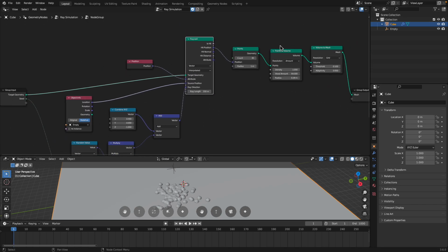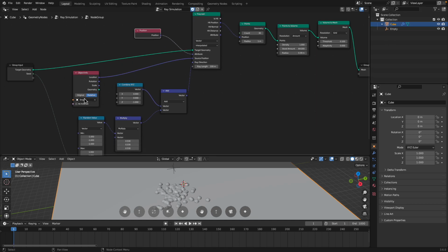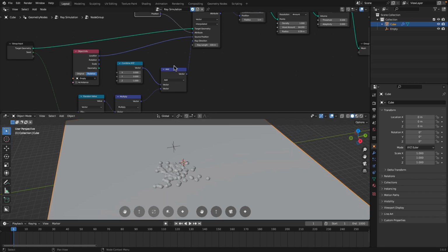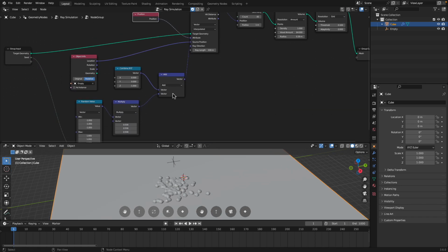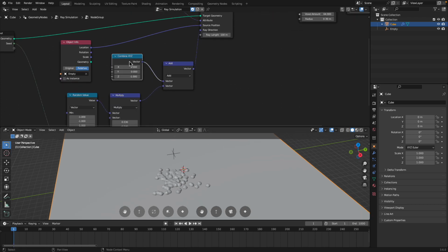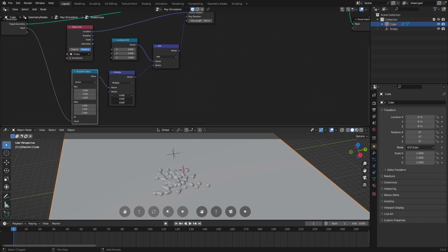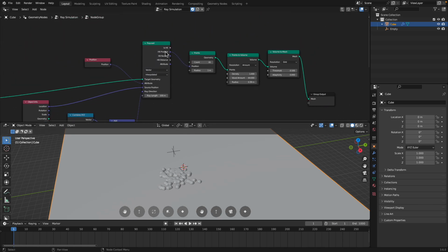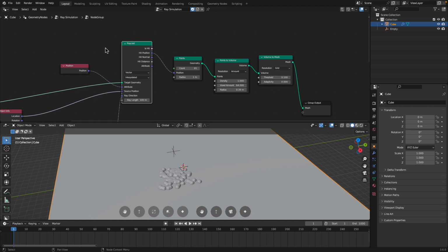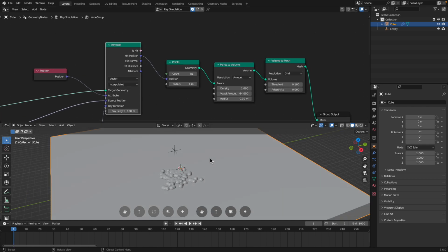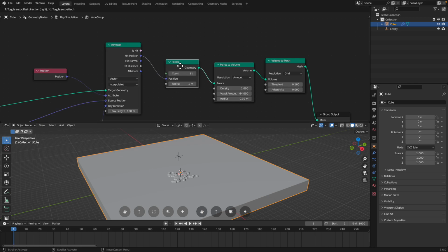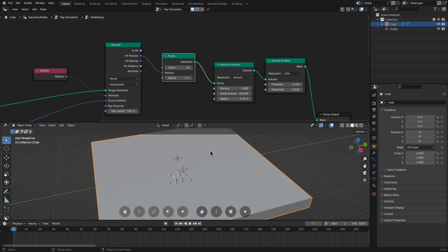This Raycast node is taking the position of the empty, and the empty is kind of spraying the points in a minus z axis that has been multiplied with a random value. So I can control the spray. The output of this Raycast on a hit position, that's hitting the ground, which is this default cube, is going to spray a bunch of points. I can specify maybe 20 points, so fewer points now.